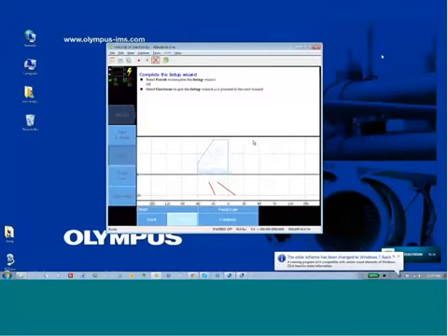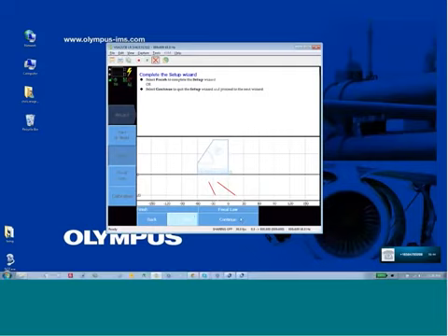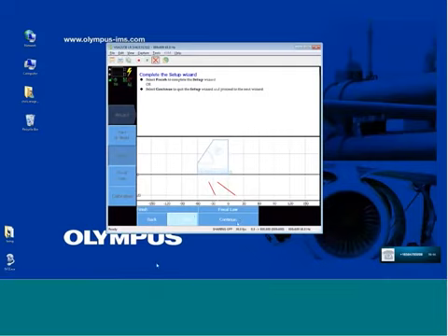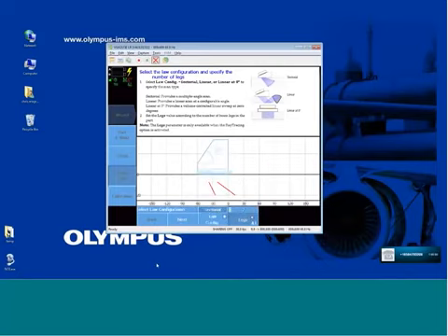So at this point in the software, we completed the setup wizard, and now we have an opportunity to continue to the focal law setup here, which would be the same thing as the focal law setup here. We select continue, and we can ask for either a sectorial or linear scan. And for the ray tracing, either 1 or 2 legs to be seen in the plotter.